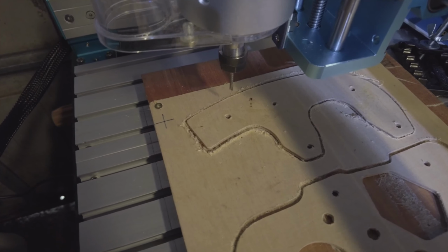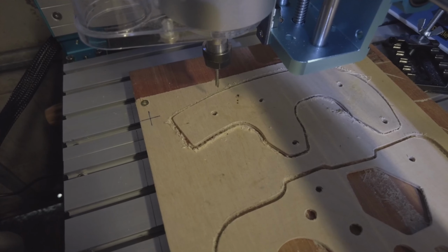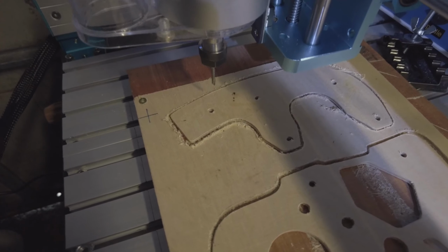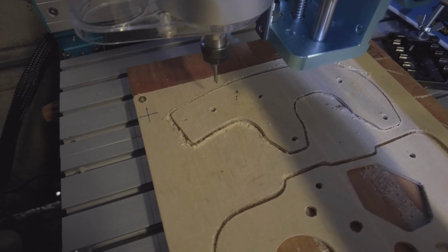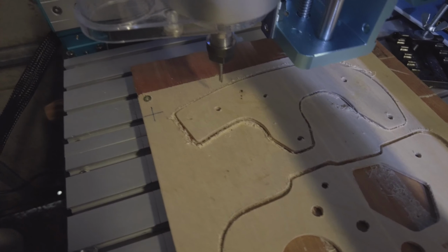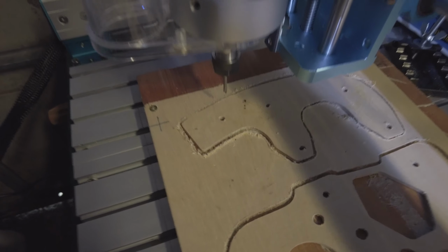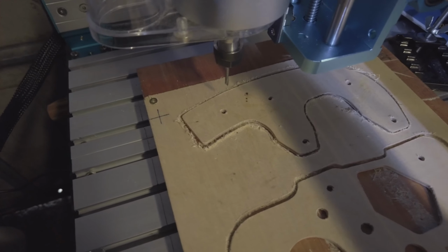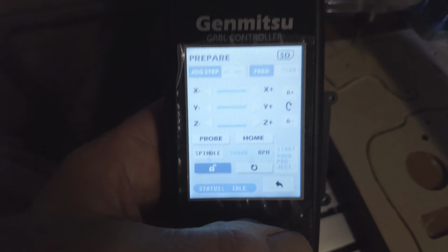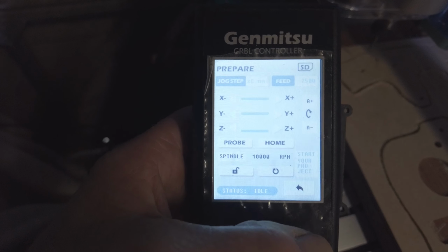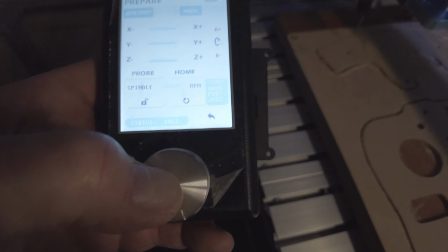and I'm going to use the touch off probe. I ain't going to use it, but I'm just saying, change the cutter now, put the touch off probe down. If it's not there, it's where you can get a flat surface for the surface of your job, your workpiece. Touch off, and that sets the Z coordinates for the touch off. Okay, then we'll go back onto here, and then what we do then is we go to start your project again.